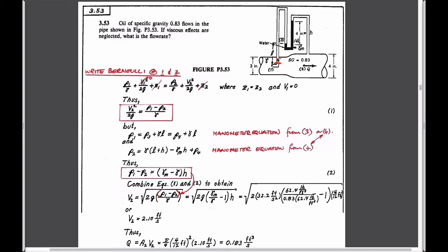So you could cut off this manometer tube here and measure a pressure here, measure a pressure here. The height difference in this case would be registered by the differences in the gauge fluid height. And so this would give you a direct measurement of fluid pressure in that case. What is called H would be equal to what? P1 minus P2 over the unit weight of the gauge fluid, which is mercury in this particular case.